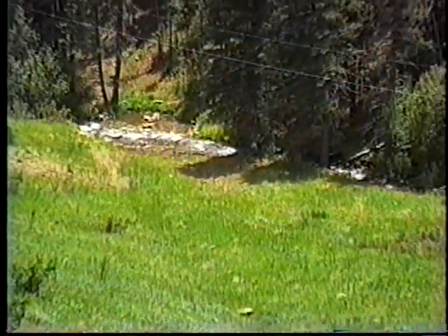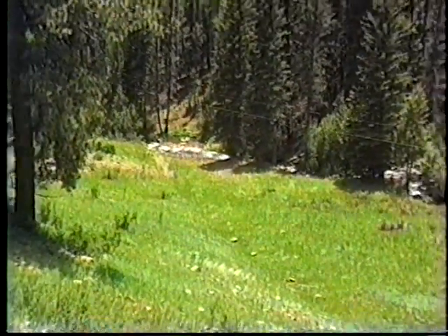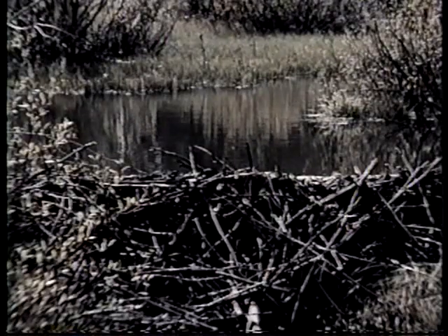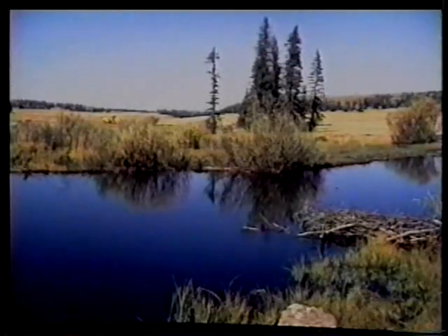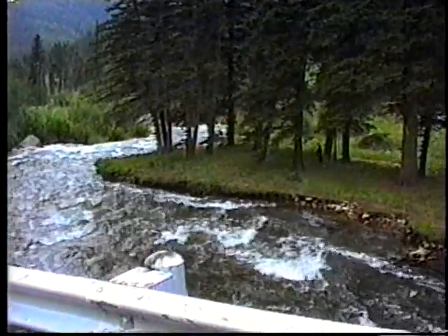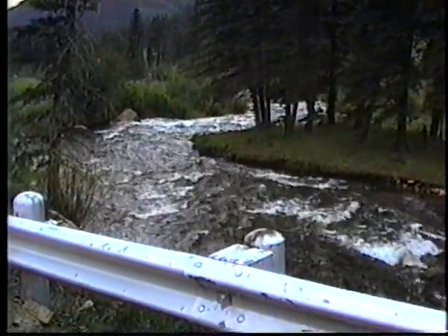In both cases, erosion control of road surfacing materials was of equal or greater importance than dust control due to the sensitive trout stream habitat very close to the roads. The first road ran through a high mountain meadow, intersecting a creek with beaver ponds and full of endangered trout. Road oil met agency criteria for an environmentally friendly, non-asphalt treatment that could be mixed in place at this sensitive, remote site.